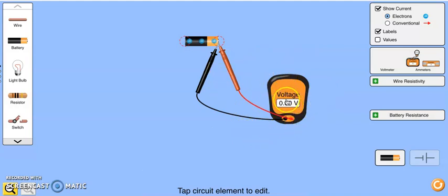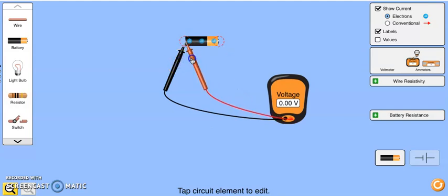Because when you measure voltage with a meter, you're measuring, again, the difference between two places. Since these two places are both at 9 volts, there's no potential difference there, so nothing happens. If, on the other hand, I move it here, I see that it's 9 volts. So there's a 9-volt potential difference between those two. Now, this might seem obvious or silly, but it's actually very, very important when circuits become a little bit more complex. It's a simple concept, but it can get confusing when things get complex. All right, and I could certainly move it here, and we'd expect 0.